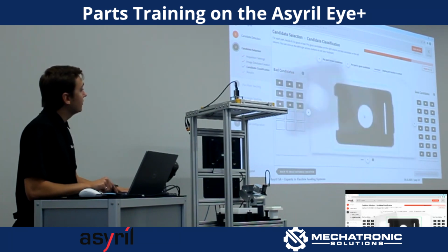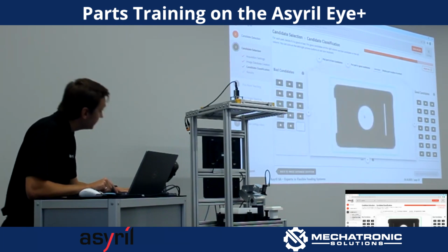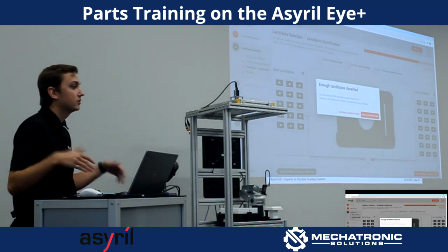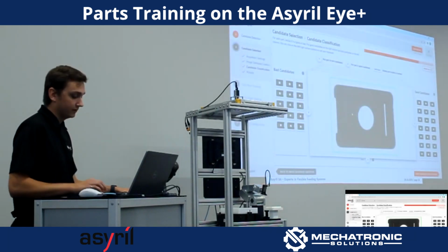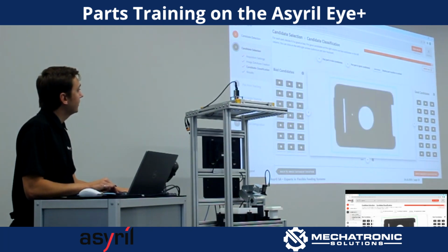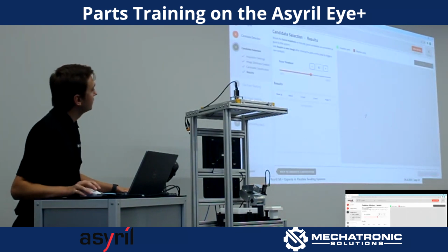The AI algorithm, this step, the candidate selection step, after 15 parts of each good and bad, it'll say, okay, enough candidates classified. It feels comfortable with making a classification, but you can always add more to boost the robustness of this step. So I'm just going to continue filling in all the parts, categorizing them. And so then we can apply classification, and it'll move to the results tab.